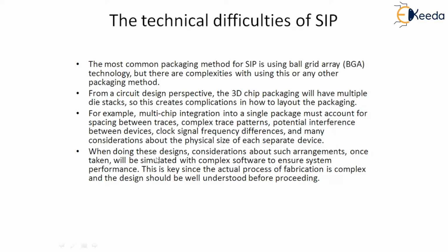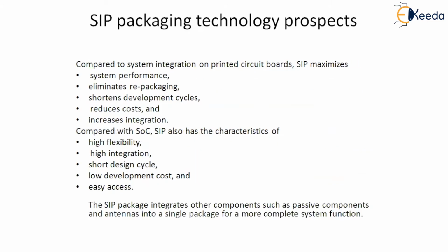For example, multi-chip integration into a single package must account for spaces between traces, complex trace patterns, potential interfaces between devices, clock signal frequency differences, and many considerations about the physical size of each separate device. So these are all the technical difficulties we have to face when we are fabricating using system in package. And when doing the design, consideration about such arrangements, once taken, will be simulated with complex software to ensure system performance. This is key since the actual process of fabrication is complex and the design should be well understood before proceeding. Okay, so these are the technical difficulties of SIP.